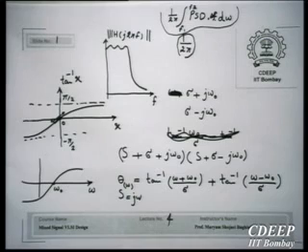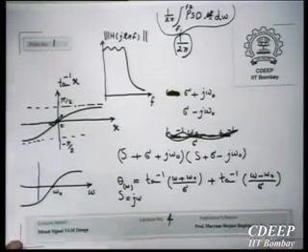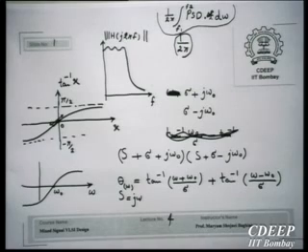And only 2 students till now have reported on this high pass filter. Both of them got infinite noise by analytical calculations, but I asked you to simulate it. If you simulate, you will see the simulator will show something different. So take care, your calculation has something wrong, okay? Again, double check your calculation. There is something specific that you have to be careful about. Otherwise, this means it is not possible to have any type of high pass filter.